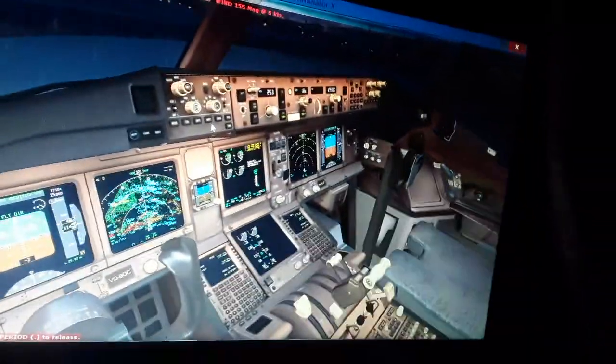I will use the flight management computer to calculate the takeoff speed. So we will use the thrust from the engines, the forward thrust propulsion, to accelerate the aircraft on the runway. So we're going to use also the runway conditions, the runway length, the temperature, the barometric pressure, the altitude, the wind direction, and if the runway is wet or dry or icy, and the temperature of the air and the pressure. So we're going to calculate the takeoff speed.